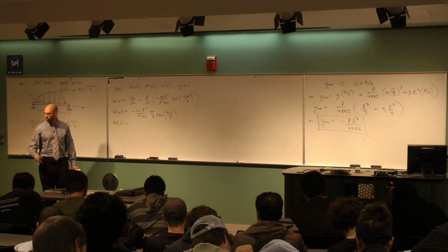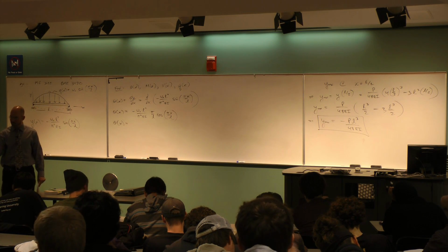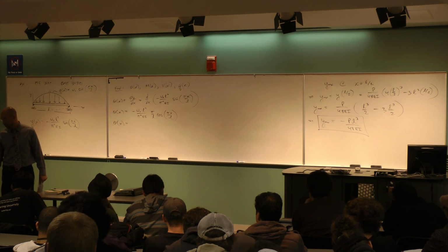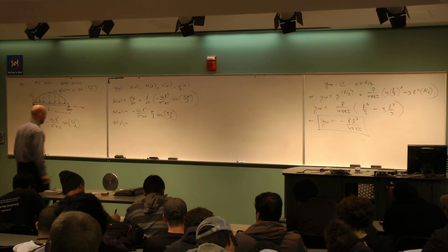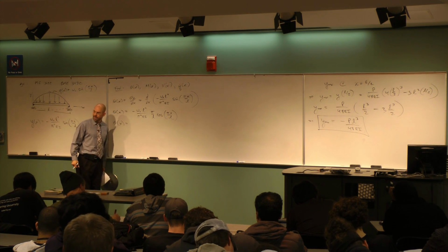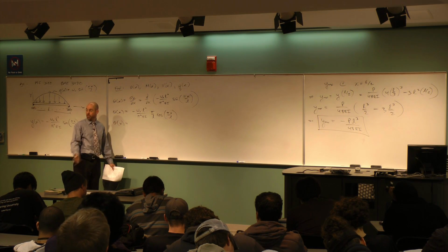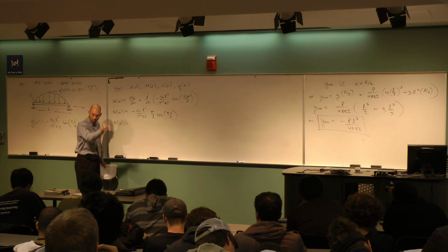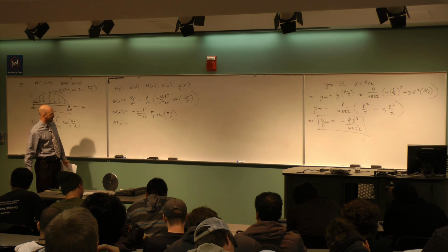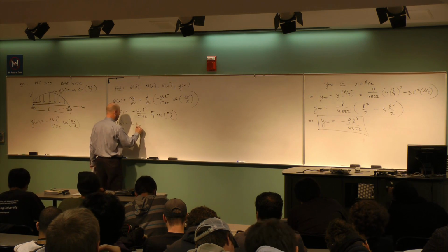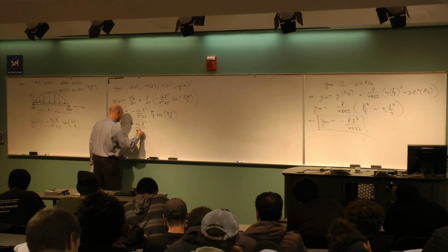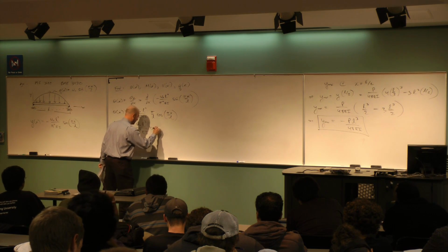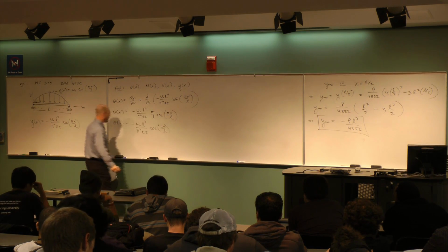L. In general, with a beam problem, if I start with a bunch of letters for deflection and I find slope, I always need to get 1 less L. That's the unit thing. This is how you get 1 less L here. In a problem that's a polynomial, I get 1 less L because when I take the derivative of an x cubed, I get an x squared. So it's a different way of getting 1 less L, but it's still 1 less L. So it's minus w naught L cubed divided by pi cubed EI, and then I still have this guy, cosine pi x divided by L. Okay, so that is theta.